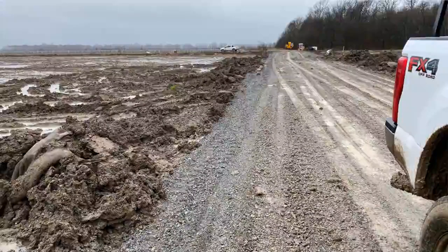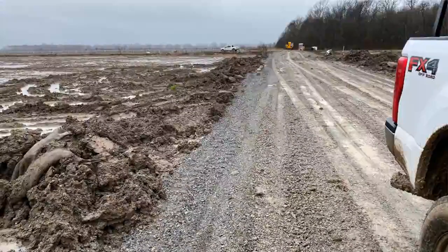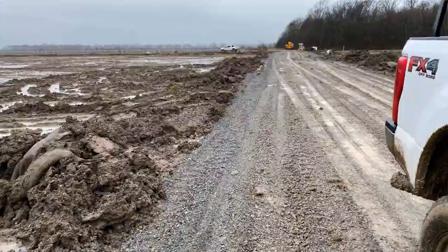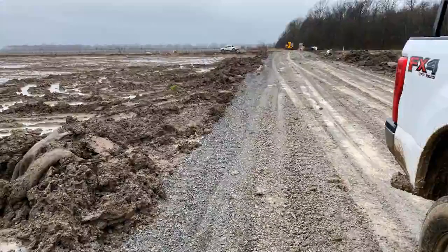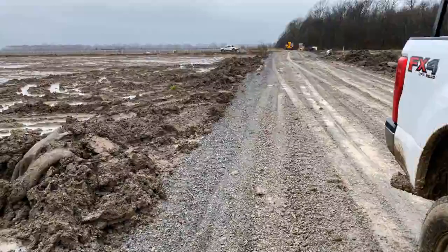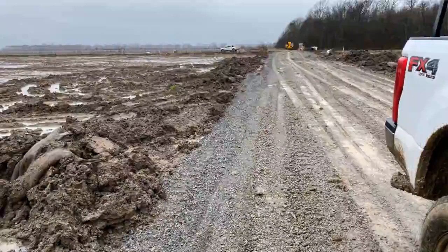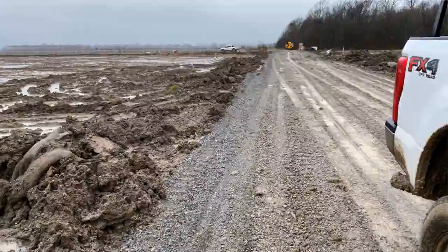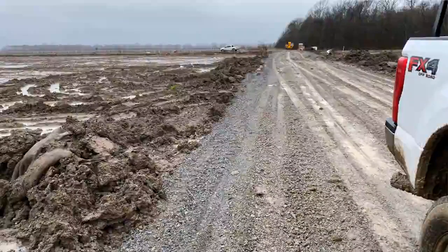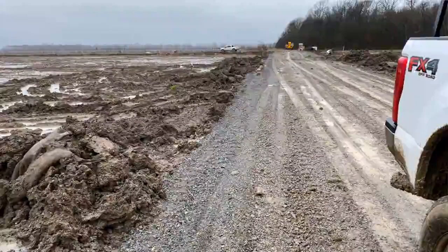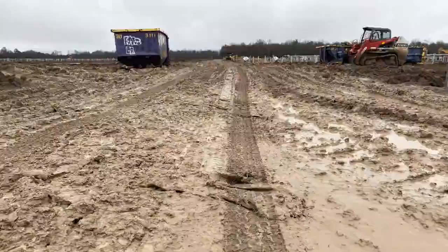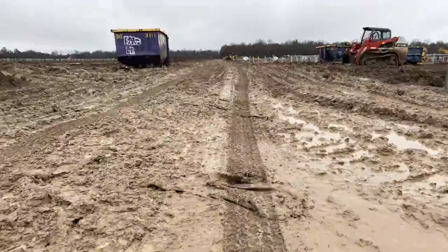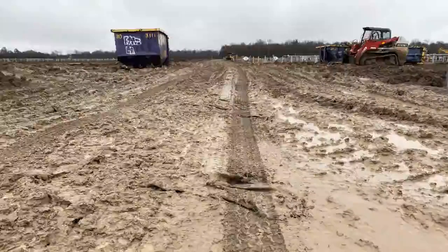So when the pile driving operation stayed ahead of the road construction, everything was going well and the 7-inch section maintained support. But as the roads got ahead of the pile driving operations, they needed some more sacrificial thickness due to the pile driving machinery tracking up that sticky clay onto the structural section of the roadway and pulling it away. In some places, the geosynthetic was exposed due to the unanticipated use by the pile driving equipment.